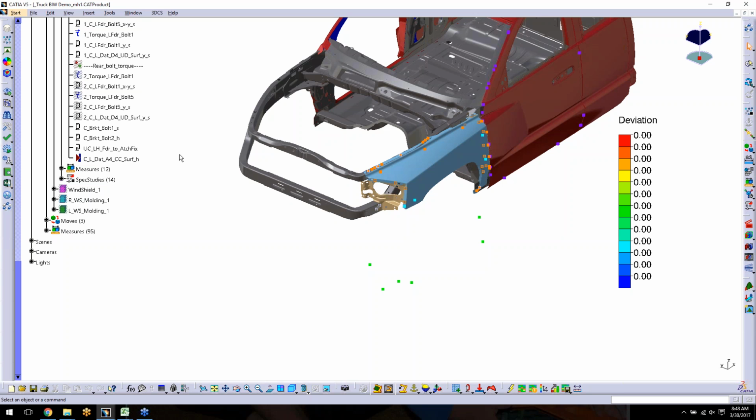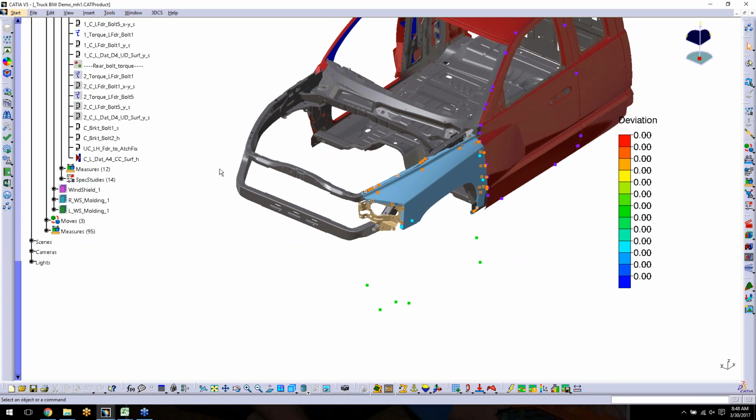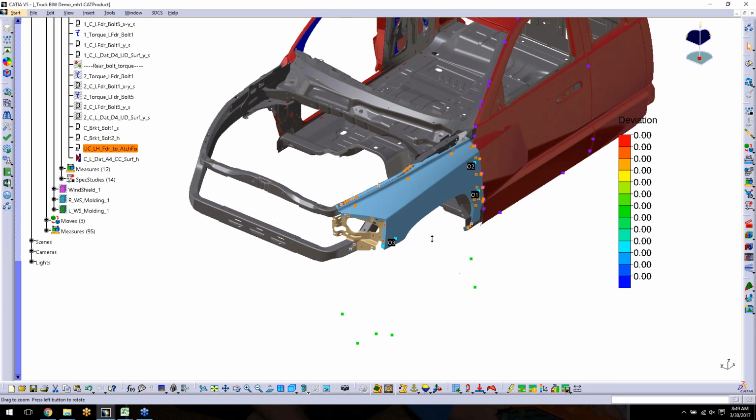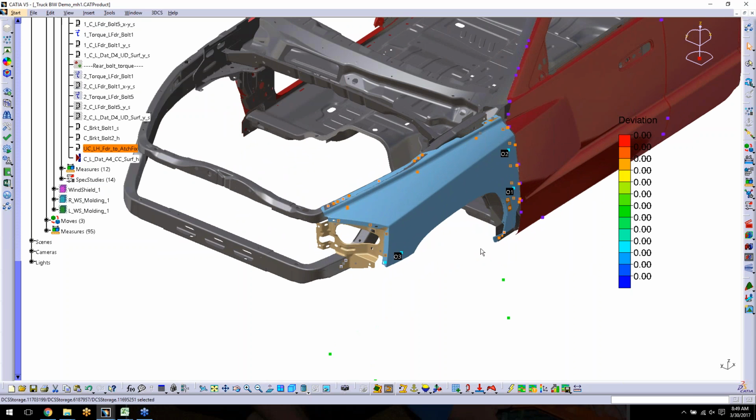So to avoid that situation, the last clamp, I made it a hard clamp. That will not influence anything that happened before in my fender, but it assures me that I have the fender staying in one place. And then I am going to unclamp the original hard clamp. Let it go. Let the fender spring back wherever it needs to spring back.